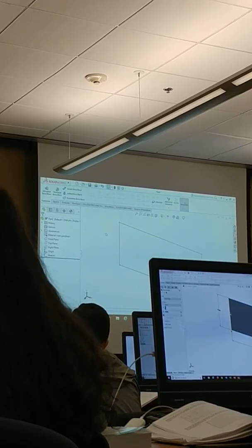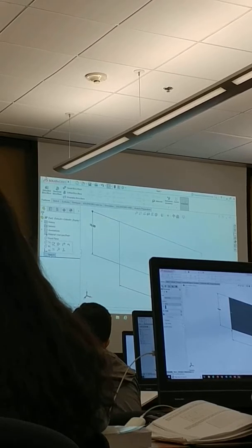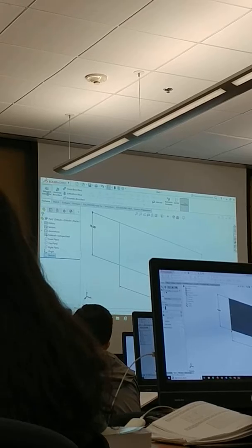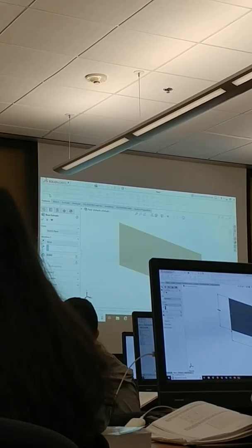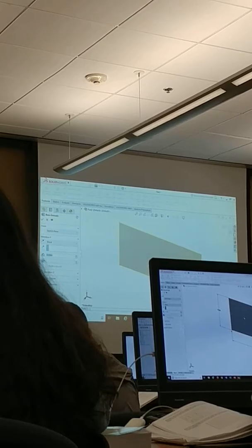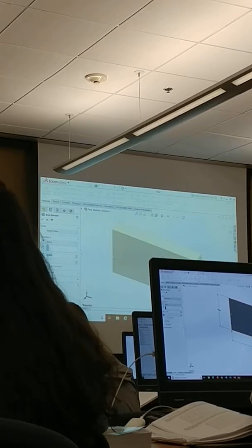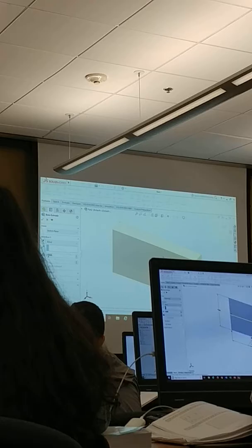Sometimes it won't. Now here's the funny thing. If I just click over here on the sketch and then go hit extrude, it knows exactly what I want because I was already selecting the sketch. So it knows I want to extrude the sketch. You have this little arrow, you can pull it in and out, or I can just say what I want. So in your flyout field, I should know that because I just said it, 10. And so now I can make it drafted.